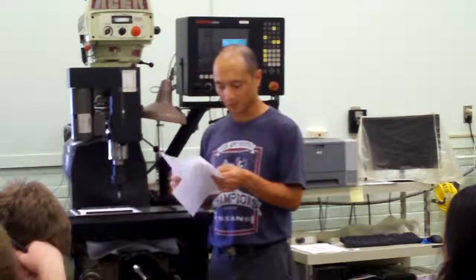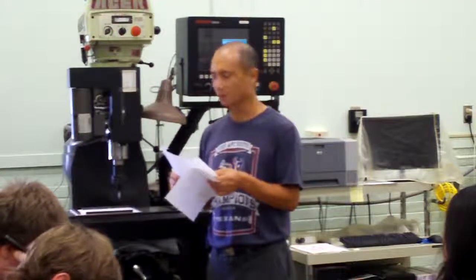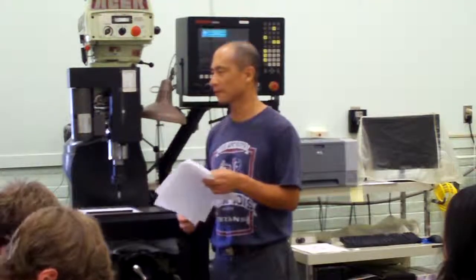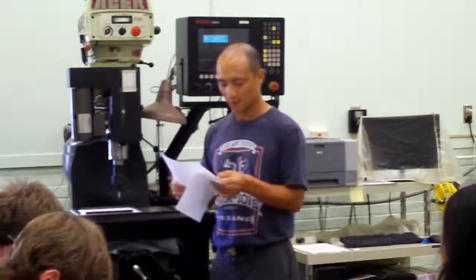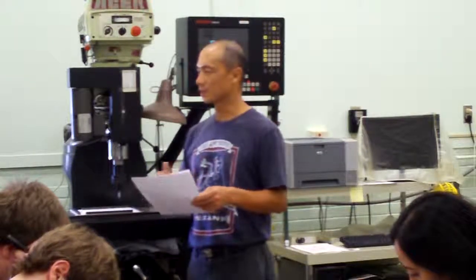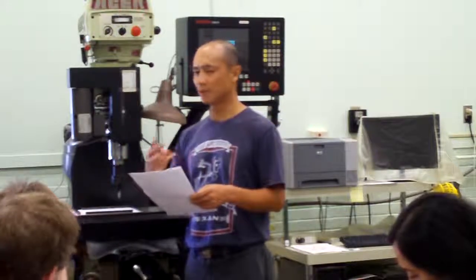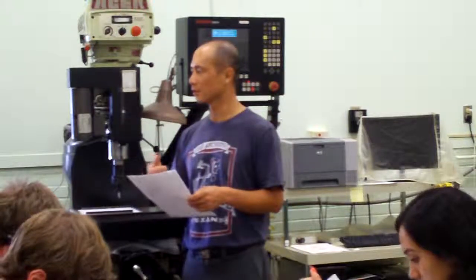Okay, G90, then also G0, Z 1.5, you simply lift up the pen by 1.5 inches. And N120 is the M code M2. M2 just tells the machine this is the end of the program. The other function it serves is to bring the cursor, or the focus, back to the starting point.